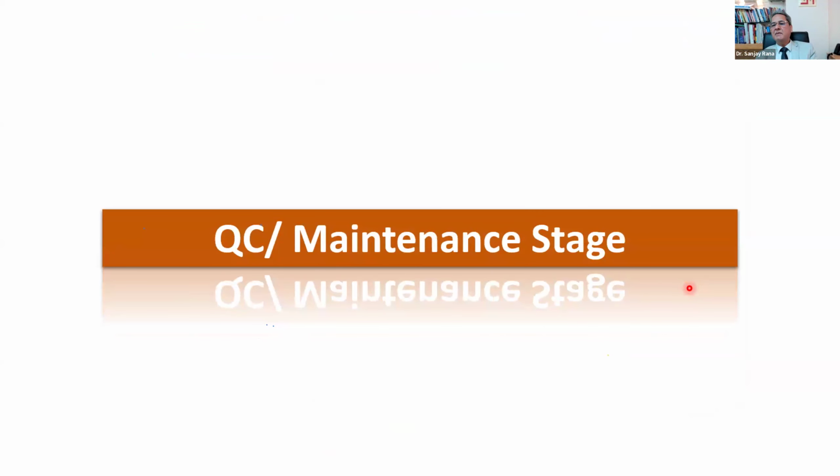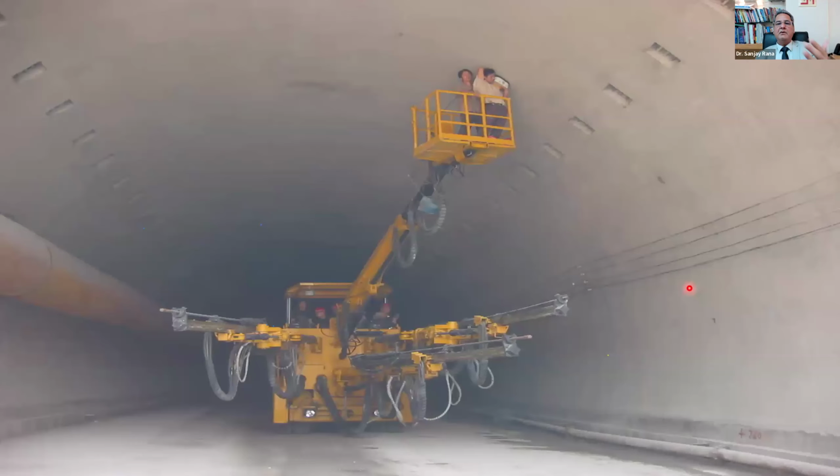Last part is the QC and maintenance stage. The tunnel has been built, but whether it is all in good condition, there you have things like GPR, which you can use in your built-up tunnel to see if there is any cavity or void behind your tunnel lining.